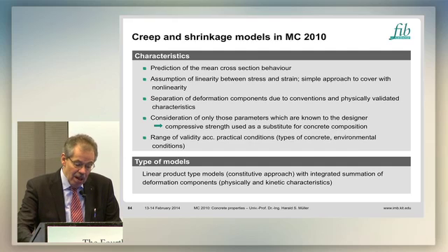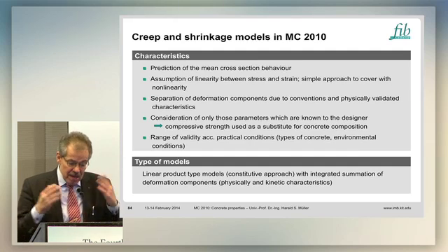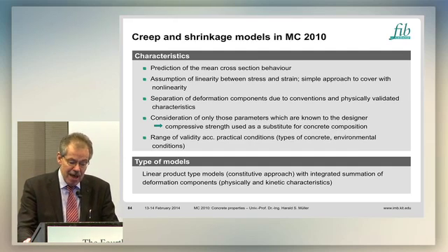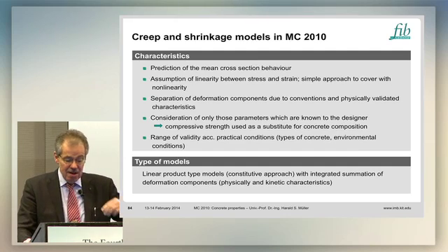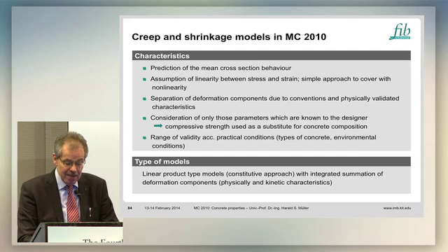And, well, the range of validity are according to the practical conditions on site, types of concrete, environmental, and so on. Well, and then if you look which type of model you choose, we selected a linear product type model concerning the conservative approach with an integrated summation of deformation components reflecting physics and kinetics of the deformation characteristics.